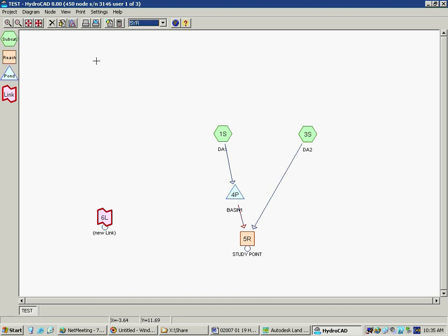Why not TR55 routing? Isn't that what some municipalities call for? TR55 is TR20 simplified, and then once computers came of age, you don't need TR55 anymore. If they require TR55, I would ask if you can use TR20.